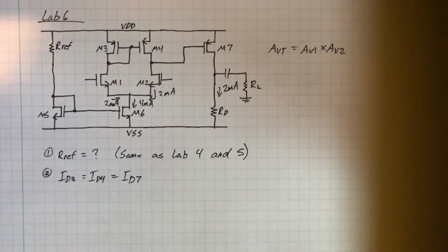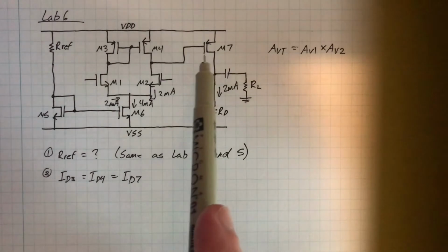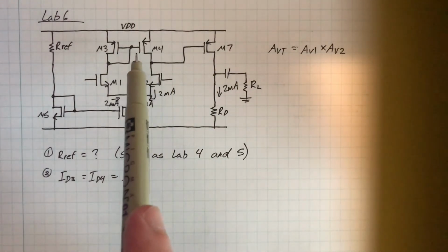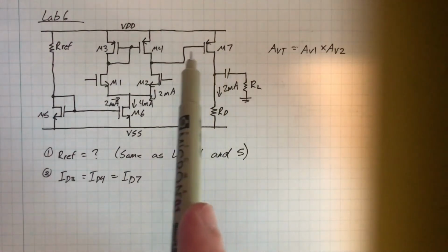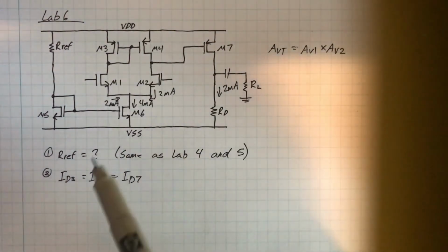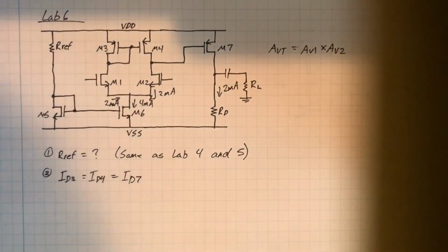You'll find in the lab that that's not entirely true because each chip only has 2 PMOS and 2 NMOS. So it's hard to get 3 PMOSs to match because you have to use 2 separate chips. And so you'll find that the current isn't exactly matched all the way. But it'll be as good as we can get.